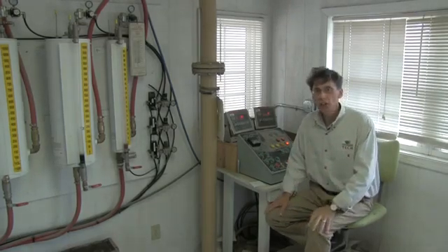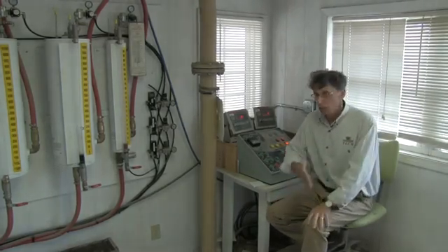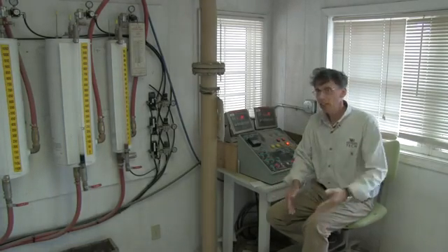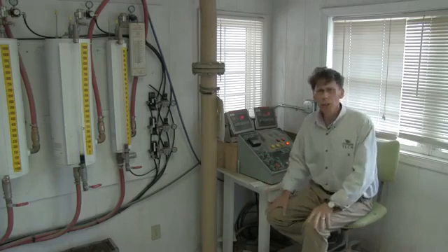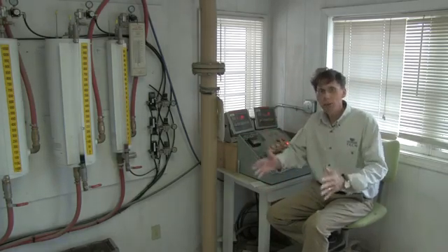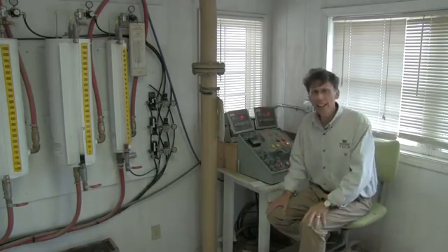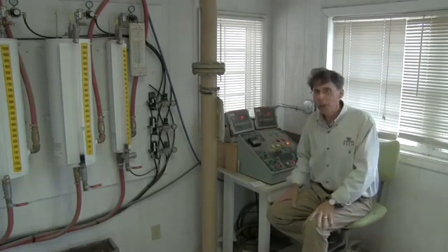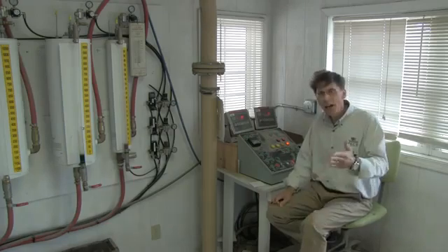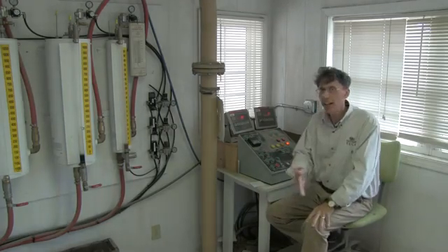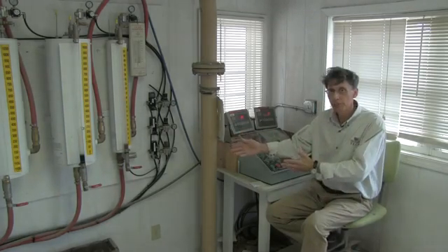Admixtures can actually alter the properties of concrete. Some will make the cement harden faster, some will make it harden slower, some will make the concrete more workable, some might actually prevent concrete from shrinking and cracking, and yet others could prevent damage from freezing of water in the porous structure of the concrete. Likewise, there are many different chemicals that are used as admixtures.